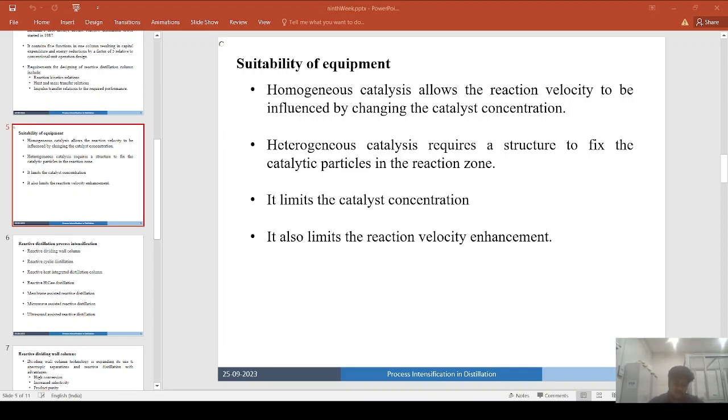You cannot use the combined benefit of both catalyst and increased temperature and pressure to increase or decrease your required reaction velocity. In the case of a catalyst consisting of ion exchange particles, even increasing or decreasing the pressure to enhance the reaction velocity will not work.